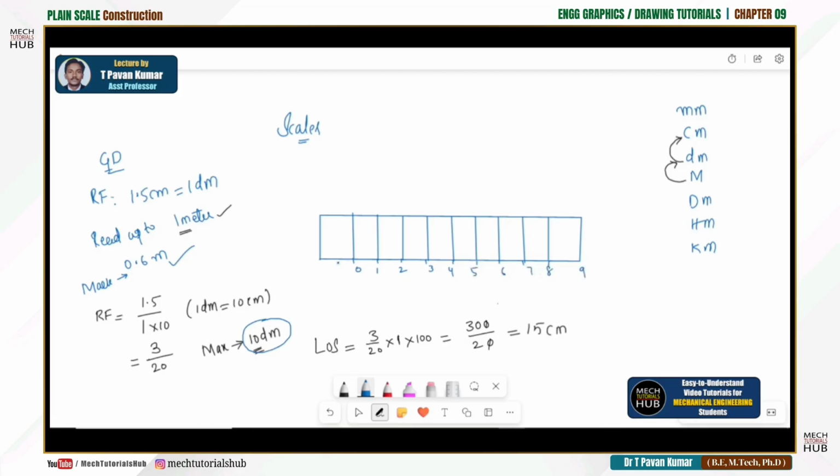Okay, the first division. Now this is a meter scale, so I have to represent two things. Below divisions, the next subunits of meters are decimeter and centimeter. I'll try to show both. This side I call deci, DECI, and this side I am calling centimeter scale. In between I'll write the RF value, whatever is given, 3 by 20. Okay, till here it is fine.